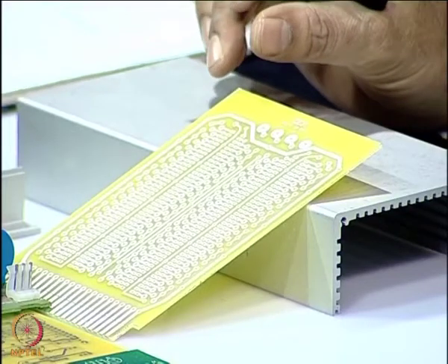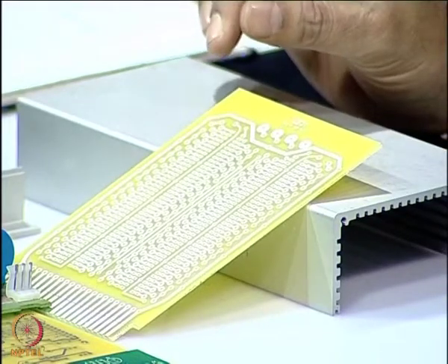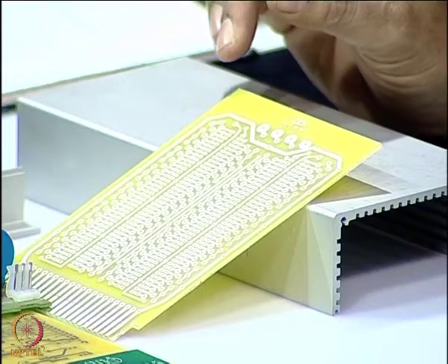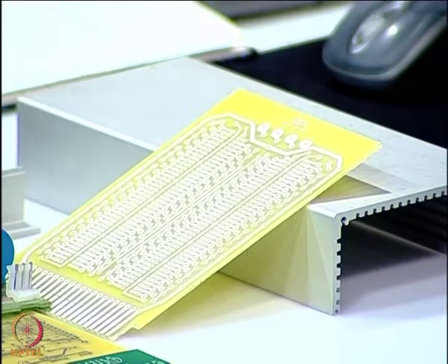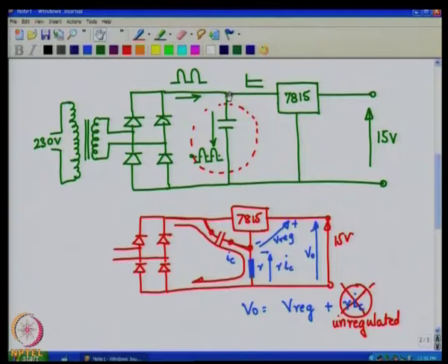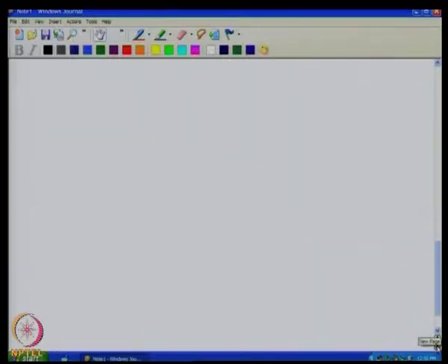Now, all these are going to give some finite resistance. So, when we draw circuit connections here like this on paper, the lines that we draw here, these lines are not zero resistance lines. These are all resistance lines, there will be resistances. As we saw here, a line that you draw here includes a resistance. So, any current flowing through that is going to cause a drop, which will have a detrimental effect on the circuit operation. So, let us have a look at the values, some numbers.